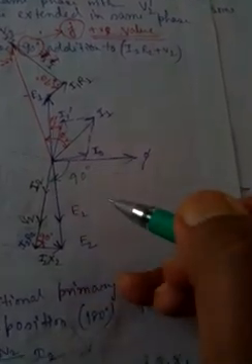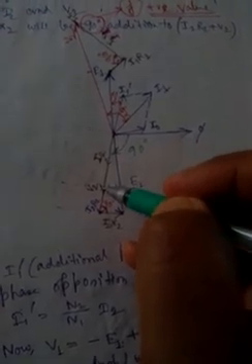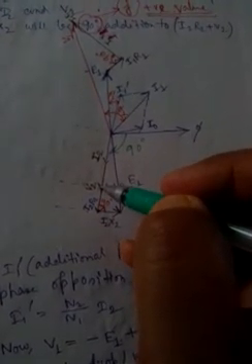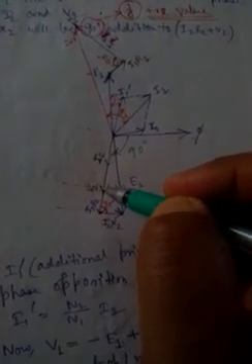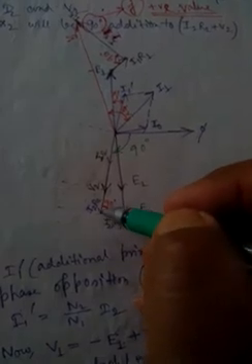Now you have to draw V2 and I2. As you know, E2 equals R2 I2 plus jI2 X2 plus V2. So you take one assumption, you draw V2, and you draw I2, and V2 and I2 will be in the same phase. E2 is equal to what? V2 plus I2 R2.